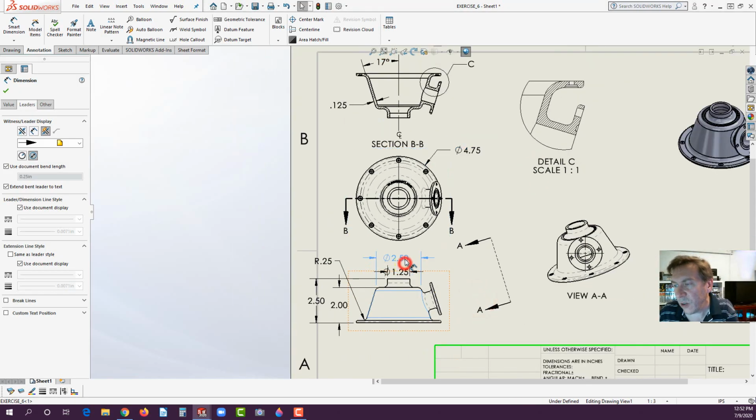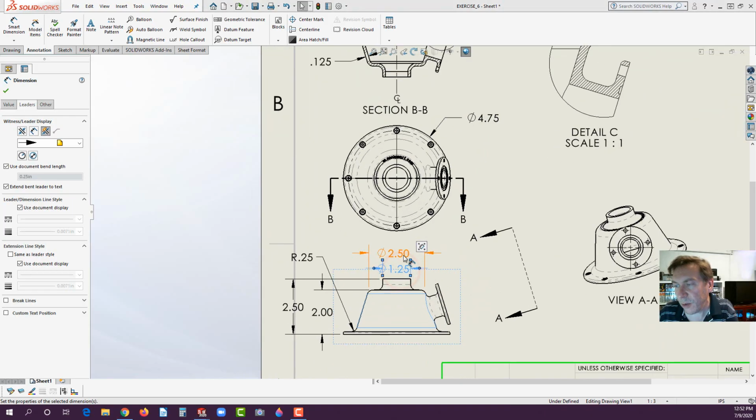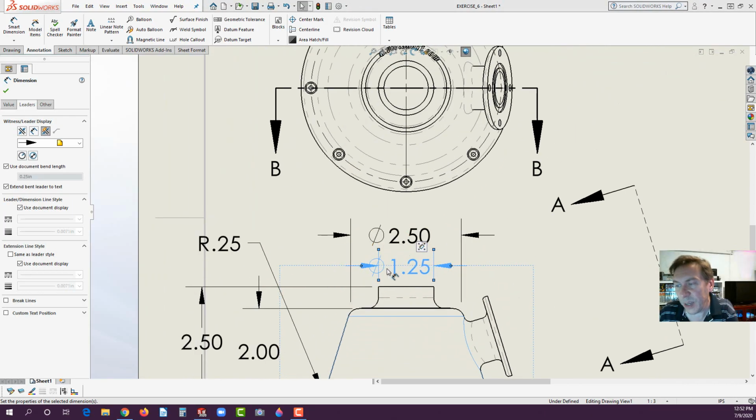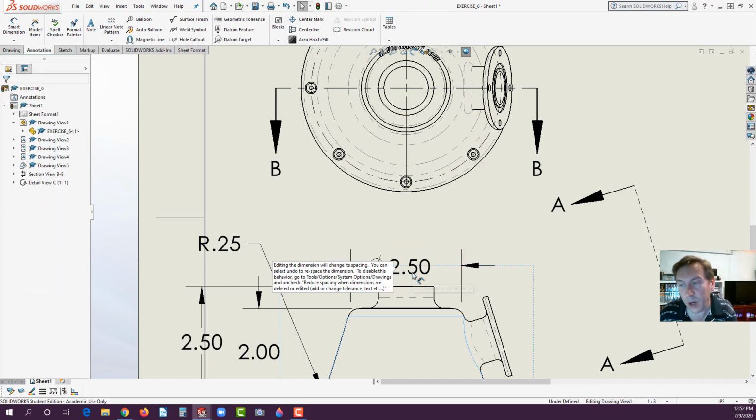Okay, let's say we also wanted to delete or hide a dimension. You could click on dimensions that maybe you don't want here, like maybe you don't want this. You could hit Delete on your keyboard. Now by clicking on Delete, that doesn't actually delete it from the model. It just deletes it from the view, and you could retrieve it again if you'd like.